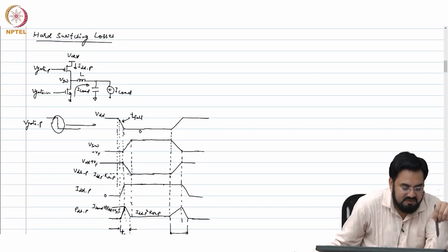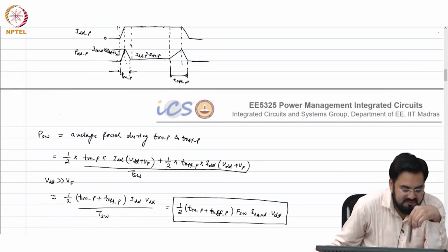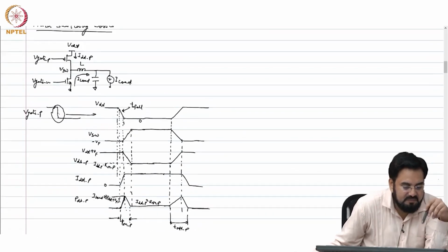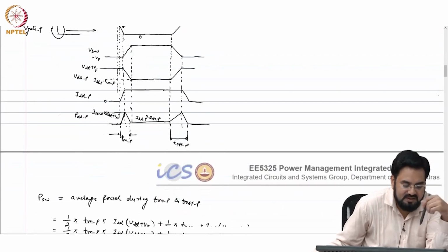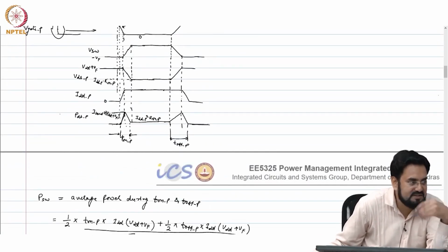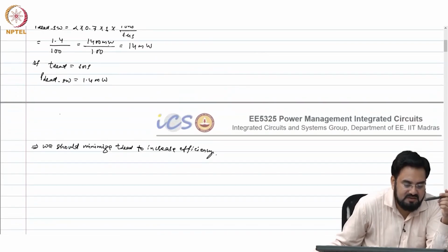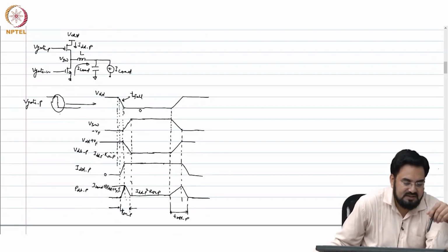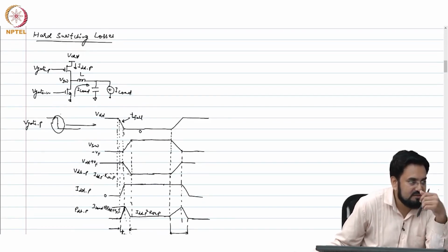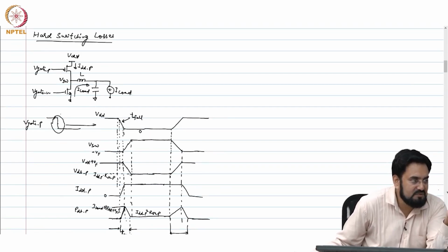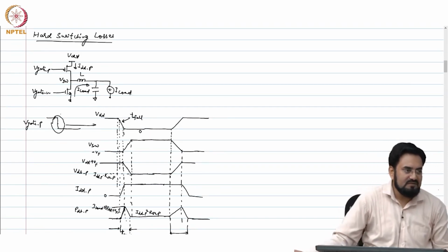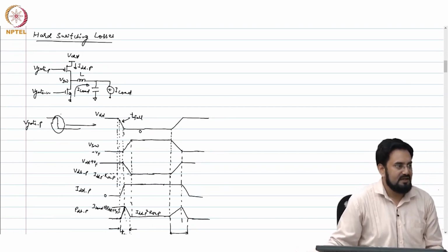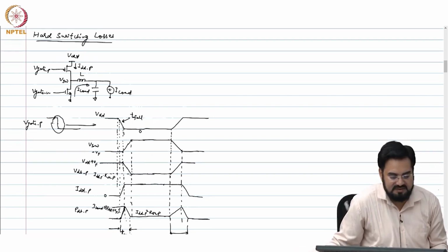But you have to remember, this is a significant factor for the external FET, but when you are using on chip, then this may not be significant as compared to the previous losses like dead time losses and gate driver losses. The reason is these on chip MOSFETs are very fast, so they can turn on much faster compared to the external FETs, which have other parasitics and intrinsic delays associated with them.